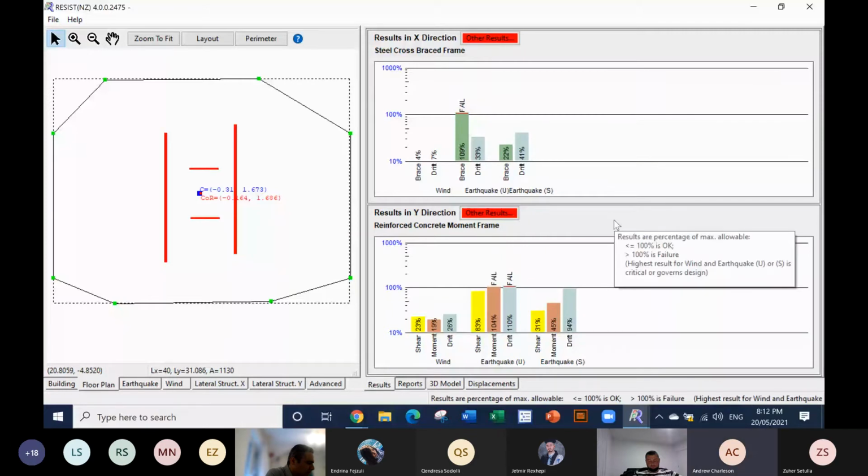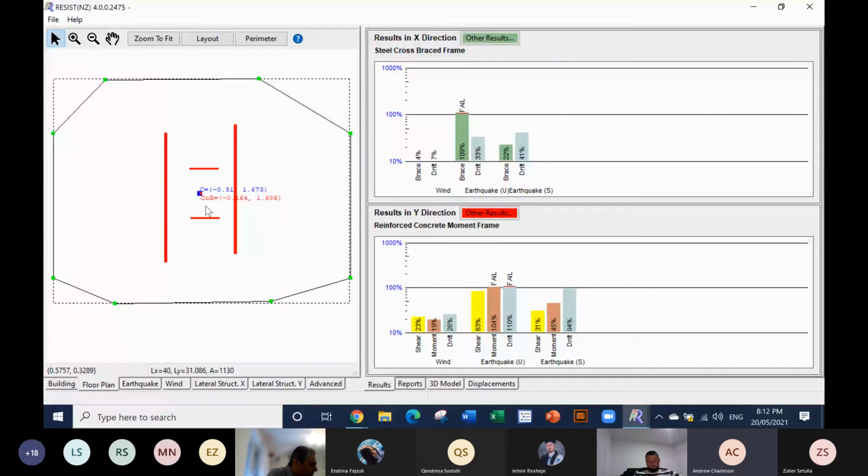And also it gets more highly stressed. So you'll see that now I've brought these elements into the core, they fail. You know, they're not strong enough. The brace isn't strong enough, and the moment frames are not strong enough. And so if your structure resisting lateral loads is in the core, yes, your building is far more torsionally flexible and more torsionally unstable. And so the principle always is, if possible, have your structure towards the perimeter.